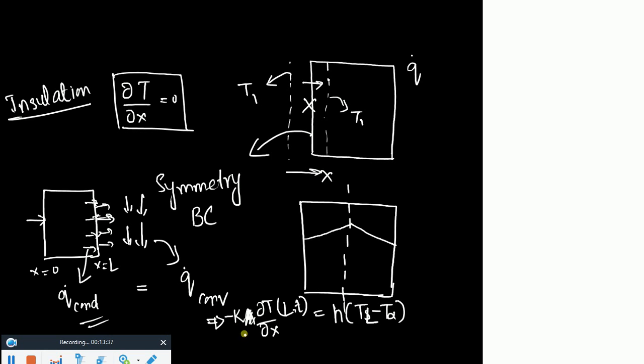Okay, so this is the boundary condition if you have conduction on one side of the surface and convection on the other side. This is quite simple. Now how to use these boundary conditions? More effectively we would use them in numerical techniques, the finite difference method on these types of problems.